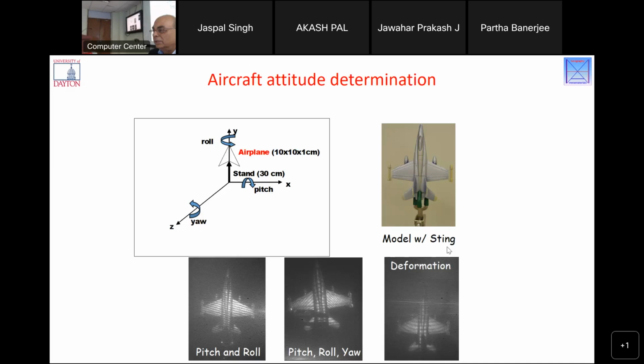The whole thing can move all the way starting from here. So you can compensate for that. Sure, that can happen. But you have to start somewhere. Before that, they did not have too many of these interferometric techniques to measure the pitch, yaw, and roll. Typically, the wind tunnel is a closed wind tunnel. So for this, they had to cut windows on the side because the laser light has to go and fall. So there are small windows that were cut.